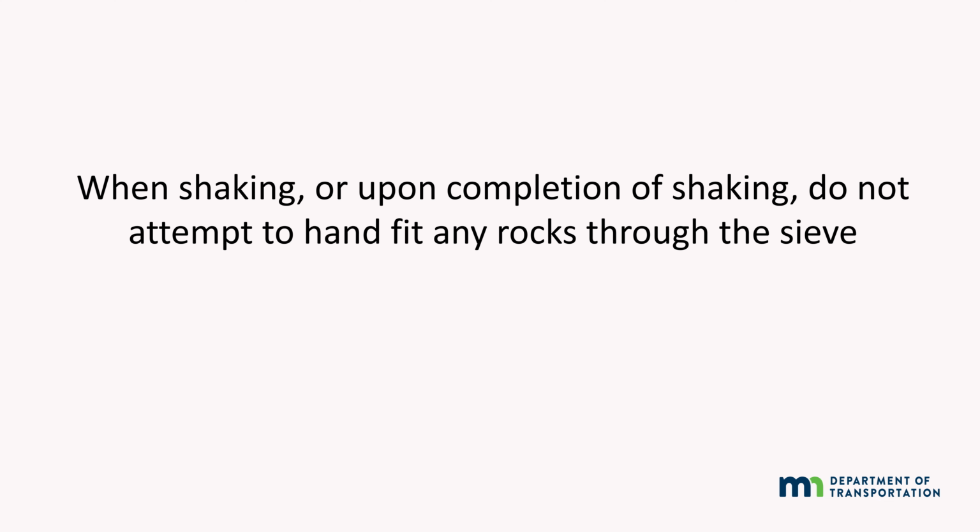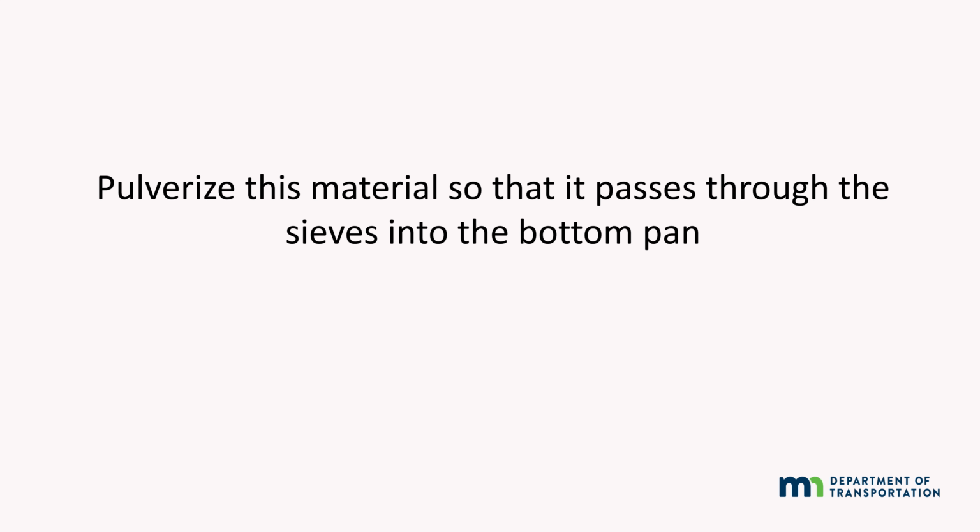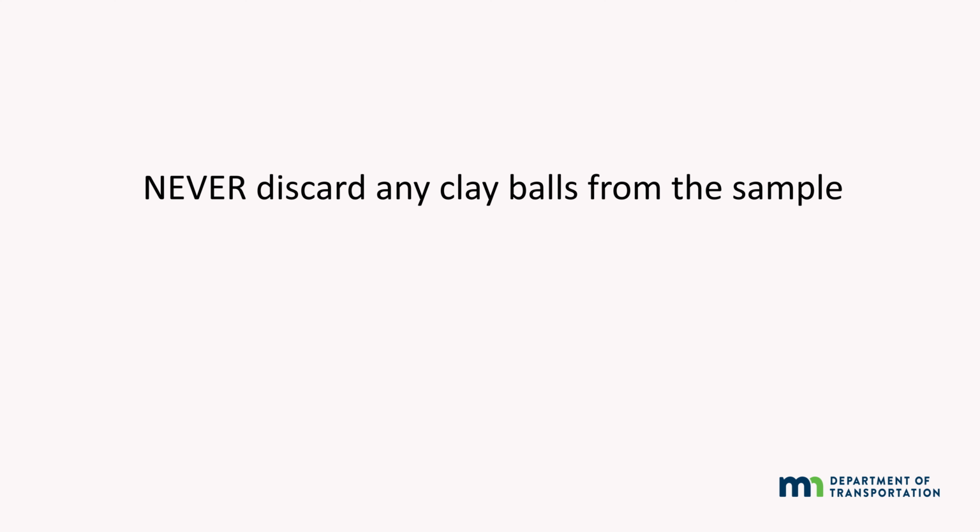When shaking, or upon completion of shaking, do not attempt to hand fit any rocks through a sieve. Once shaking is complete, examine each sieve for soil lumps and clay balls. Pulverize this material so that it passes through the sieves into the bottom pan. Never discard any clay balls from the sample.